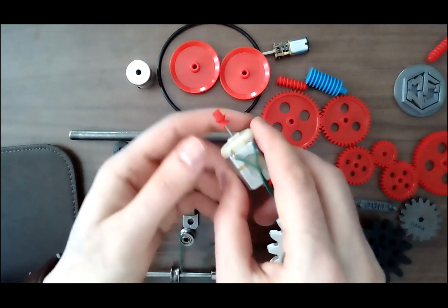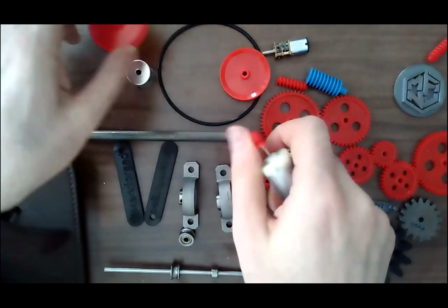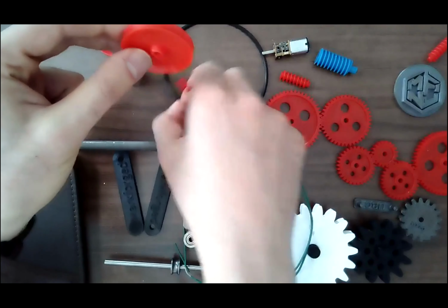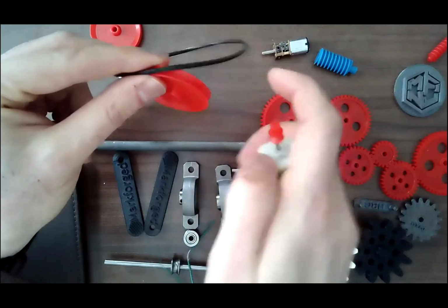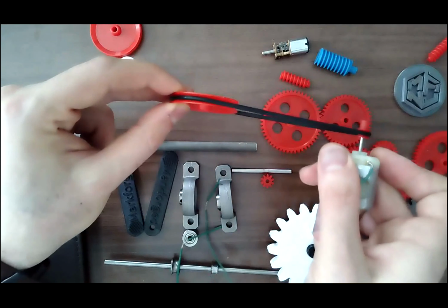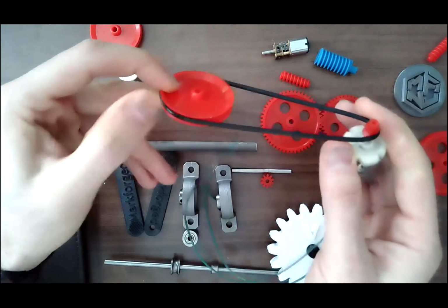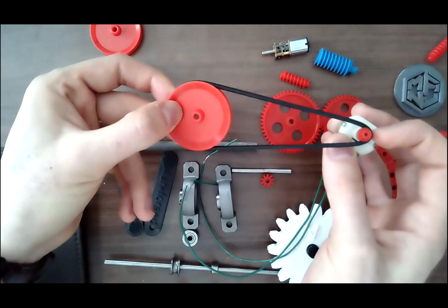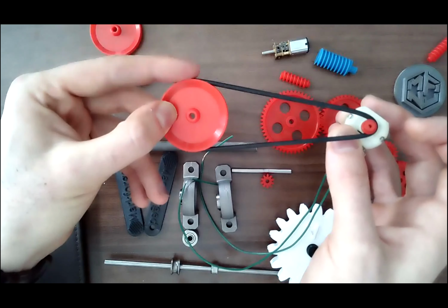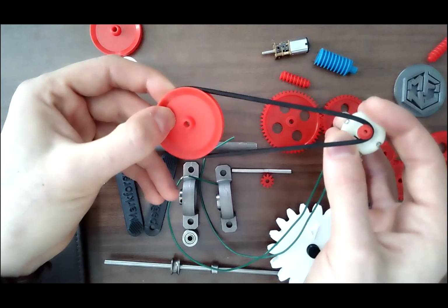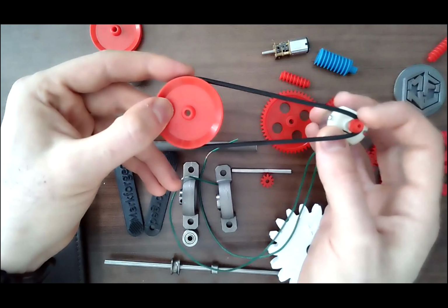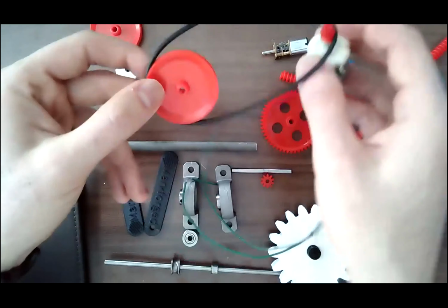So the initial solution is to use a belt and pulley, like two pulleys like that, and a belt around them. Like this. And here is the top view. Now from a small radius getting to the larger radius, the larger radius gets a small angular velocity, but larger torque. So I'm transferring power from one shaft, which is the motor, to another shaft here.